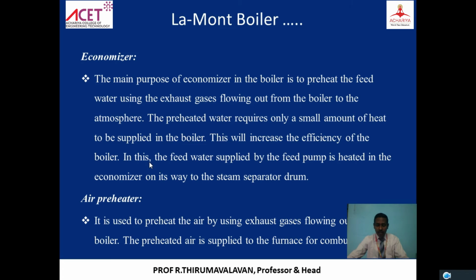In this, the feed pump pumps the water to the header of the economizer, on its way to the separator. Before going to the steam separator, the water is preheated.